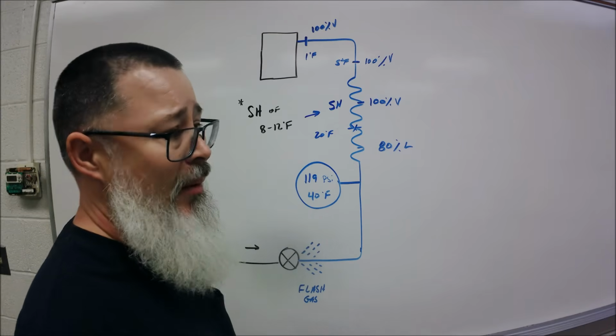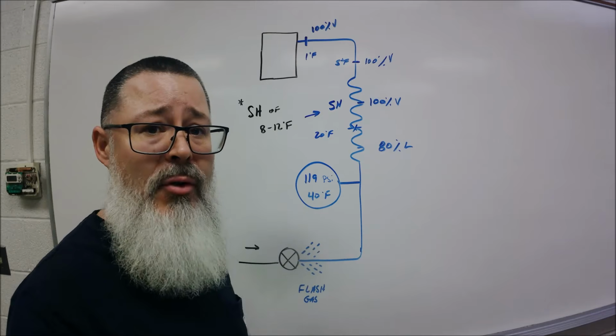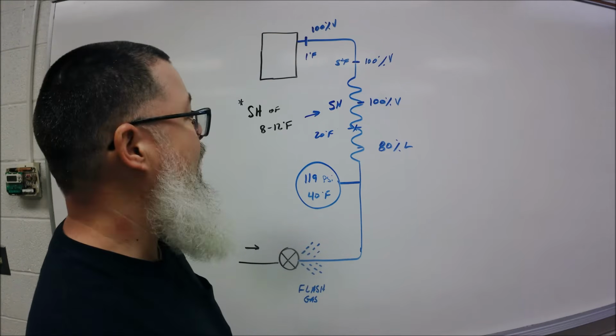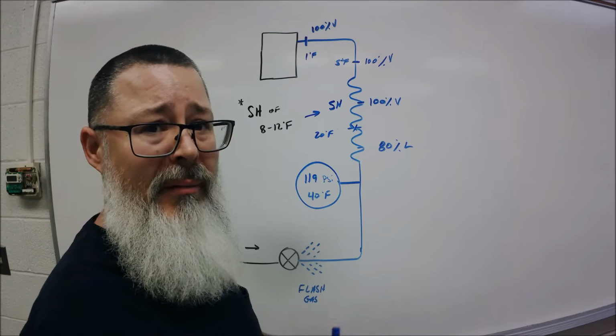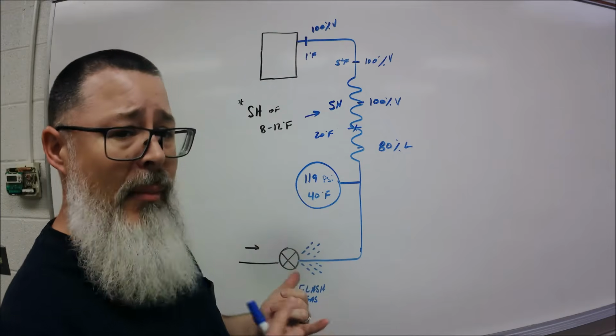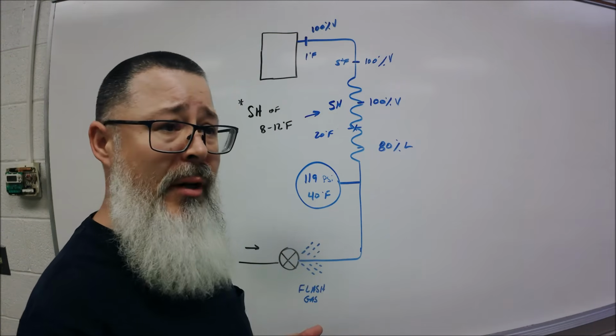We had guys that get like 40-degree readings and stuff like that for superheat. If you do the formula, you can get hundreds of degrees of superheat. But that's the math formula. That's not kind of realistic. So just understand that with superheat, it's heat above saturation, which means we have turned all the liquid refrigerant into vapor.